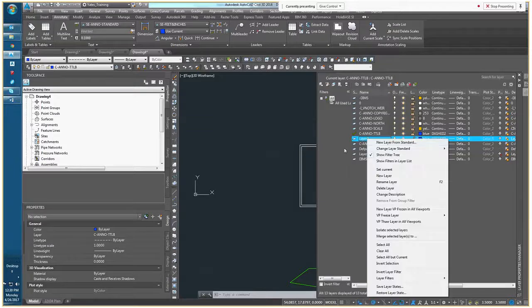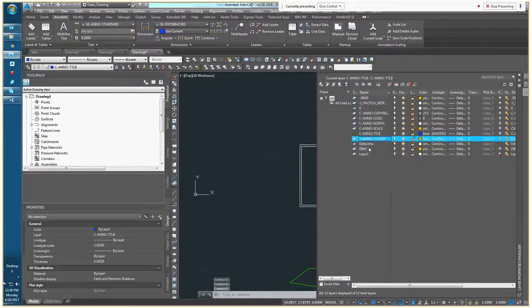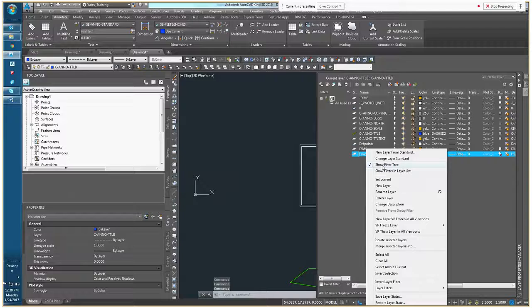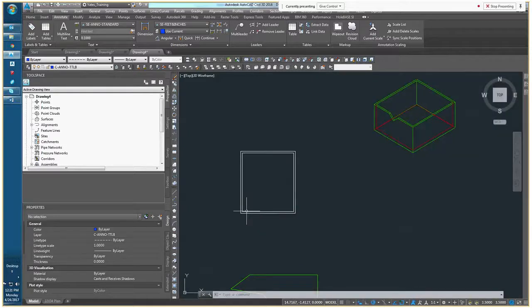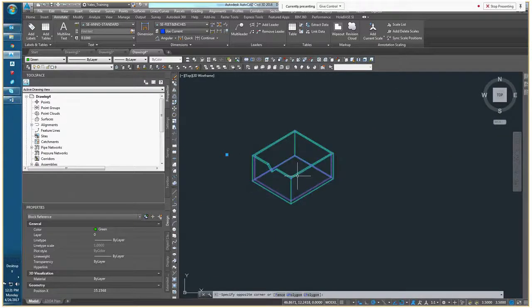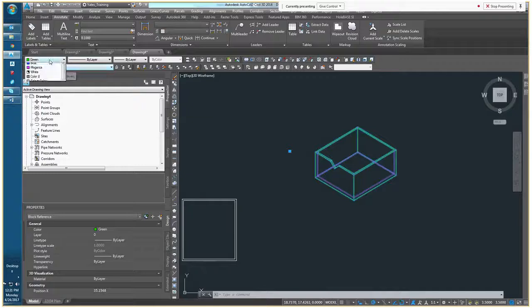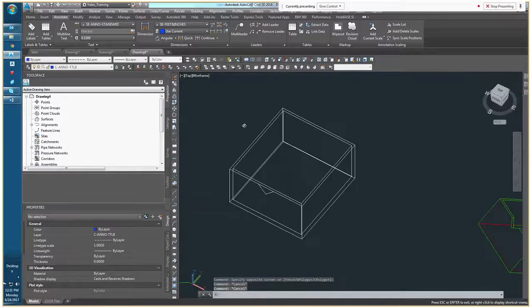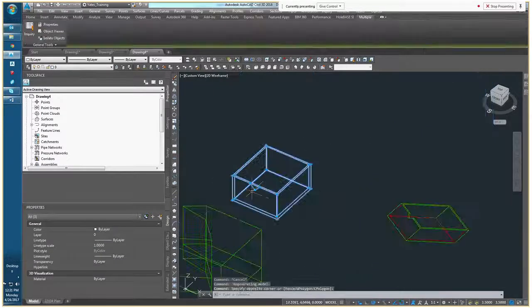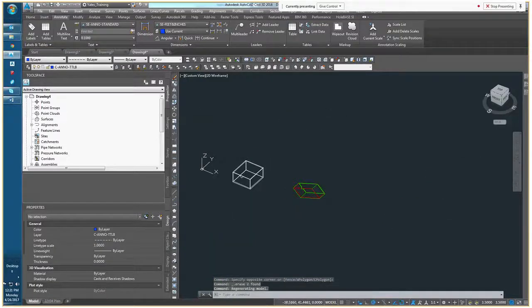Okay? Now I'm going to delete layer 2 and delete layer 1. And I've got this new layer I_V_notch weird. Now I want this puppy to not be on layer 0 and color 0. I want it to actually be by layer and on I_V_notch weird. Same thing with this stuff. I can want all of that to be on the same layer. This monstrosity we'll just get rid of, delete.